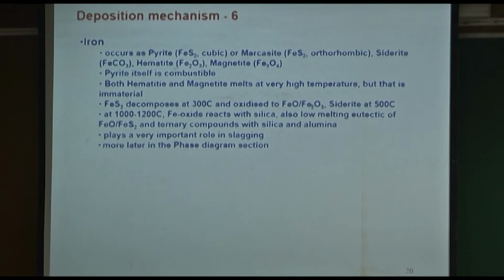These are all very well detected by X-ray diffraction, in what form iron is present. So if the boiler designer says that your iron content appears to be problematic, just initiate this analysis, give this information, and then a design strategy to mitigate the iron-induced problems can be devised.